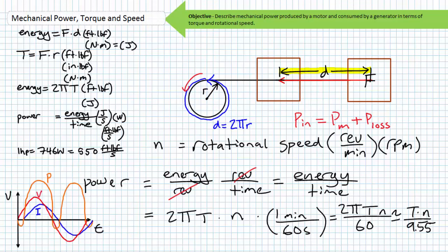Not so obvious losses, at least for those without a requisite knowledge in basic AC circuit analysis, are the reactive interchanges that can occur with some configurations of motors and generators. The very nature of all electrical machines requires an interaction of electrical current and a magnetic field, so one can expect, nay guarantee, that current will lag applied voltage for non-power factor corrected AC motor configurations. Given that voltage and current are not in phase with one another, we can expect real power actually available for conversion into usable mechanical energy to be less than what we're apparently supplying to the motor.